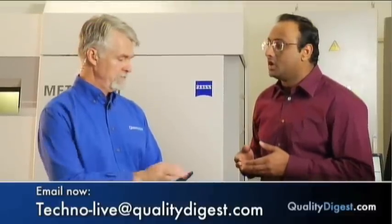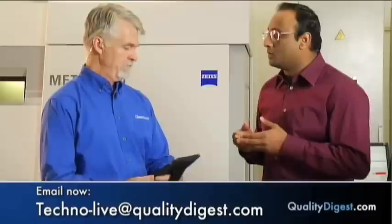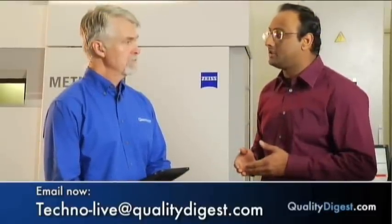Okay. In the world of CT, the most important things are a combination of size and density. As long as you have enough energy to penetrate through the part that is in front of the X-rays and the part can physically fit inside my machine, I get a good image on the detector. What makes the Metrotom a lot more unique is two different things. The two main factors involved during any CT scanning are the data acquisition and the data reconstruction. The data acquisition stage is very important because how the signal gets collected on the detector drives how accurate your data set is.